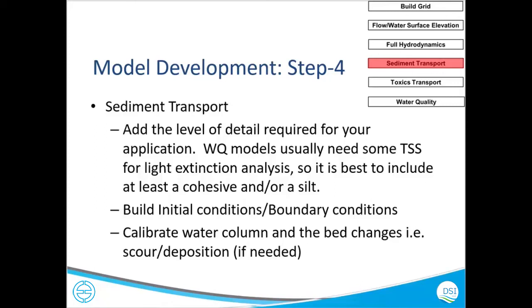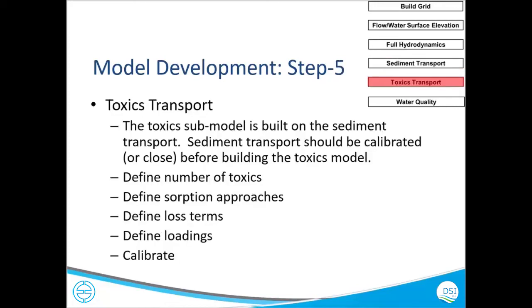And you can look at scour and deposition. So if you're expecting a deposition in some areas and you can see scour, it means somewhere your bathymetry is screwed, because it's creating an artificial pool and then water is just flowing to that particular region, and there is a lot of scour that's artificial.